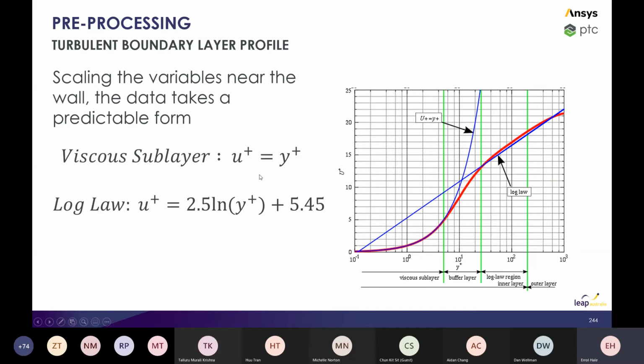And we're introducing this value called our Y+. So our Y+ is much like Reynolds number. It's a non-dimensional number. It's a function of our position in the boundary layer, which is actually calculated as a function of the Reynolds number.